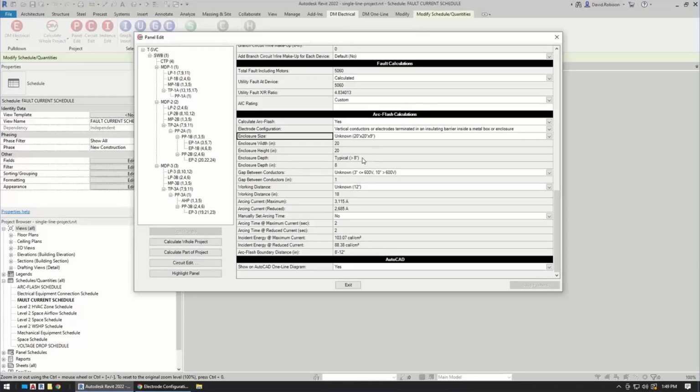Turns out that if you make the box smaller, it doesn't have space really for the whole reaction to happen, it kind of contains the whole thing, and it makes the actual final value smaller. Up to about 20 inches. You get to 20 inches, that is the optimum size if you want to maximize an arc flash. About 20 inches, it's not so small that it's constricting it, but it's still close enough that you get the reflections and everything else that it contains space. Past 20 inches, you start to approach the open air solution.